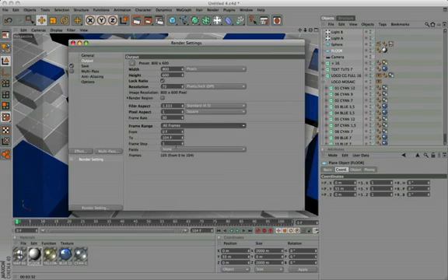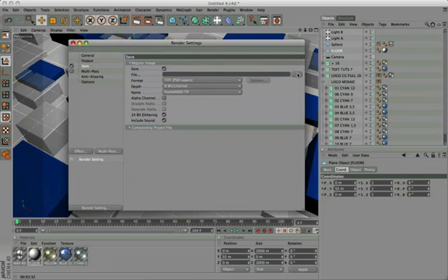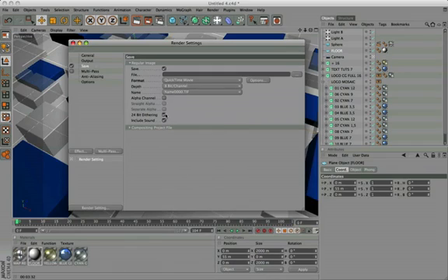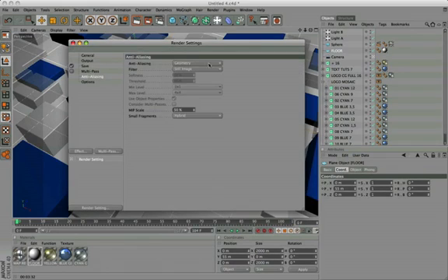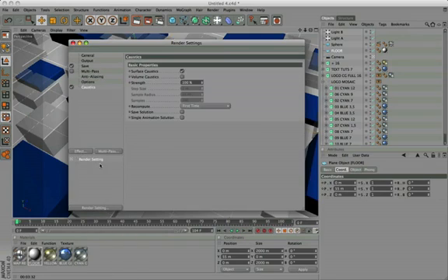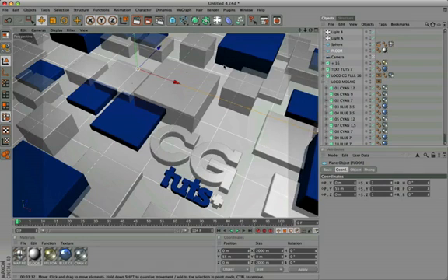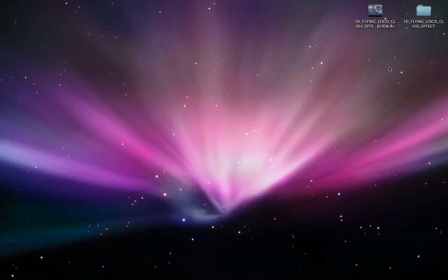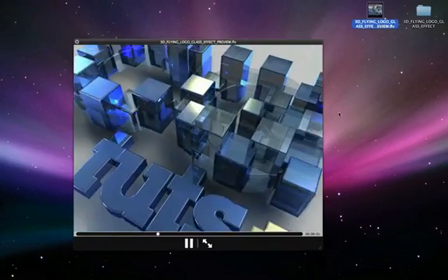We set all frames. Anti-aliasing to best, still images, and activate caustics, and check volume caustics. The rendering times are very long. At the end, we will get this result.